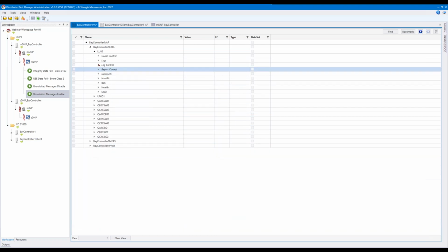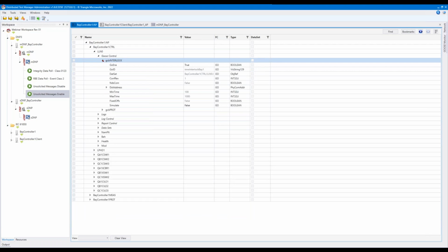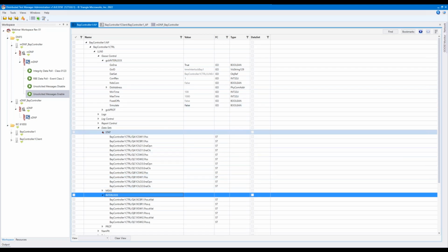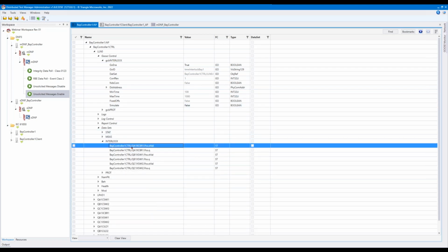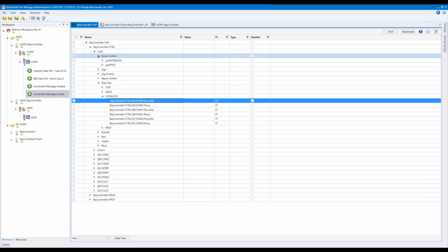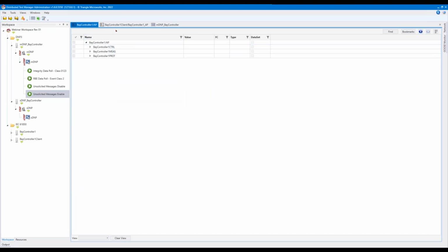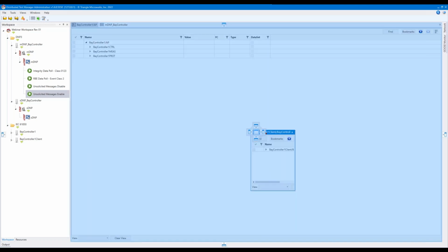In much the same way, we have our GOOSE control blocks seen up here, which have data sets as well. And as I locate those data sets, I can see the data attributes which make up the data set of my GOOSE control block. As we started out by saying, there's really 3 protocols in one that make up 61850, and these are 2 of them. The first being report control blocks that we looked at a moment ago, and the second being GOOSE. But to see these in action, I'll need to open up a 61850 client. So let me go ahead and do that, and I'll drag that down just so we can see it side by side.